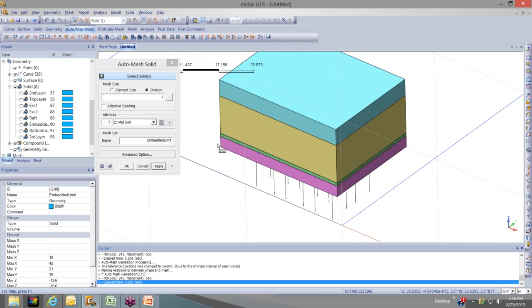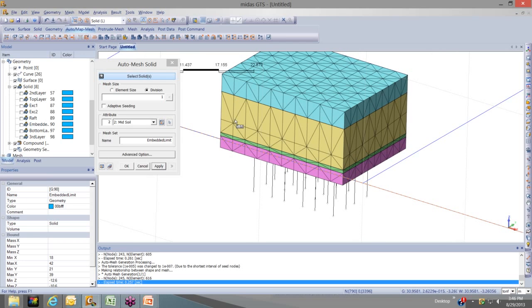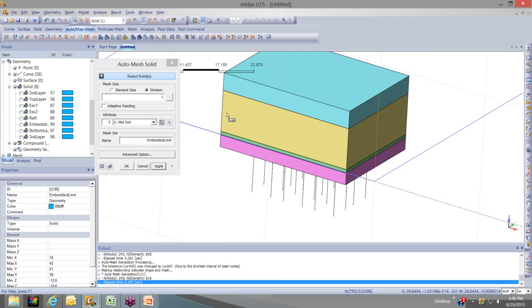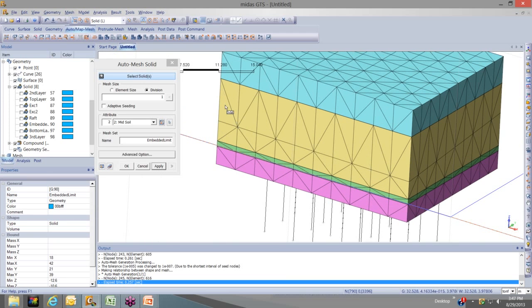Okay, so for this, what I might want to do later on, say for example I have a more profound analysis, I might want to go back and add an extra seed here, because in general, you want to avoid longer elements. So this is about, I'd say maybe a 1:5 ratio, which is passable, but ideally you'd want something closer to this, a 1:1 ratio.